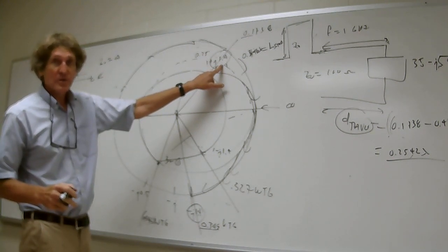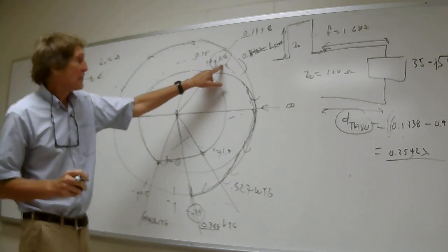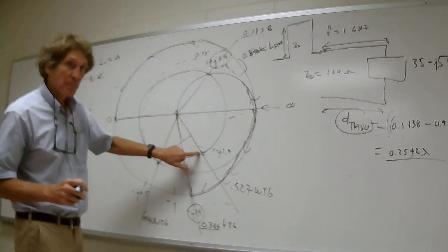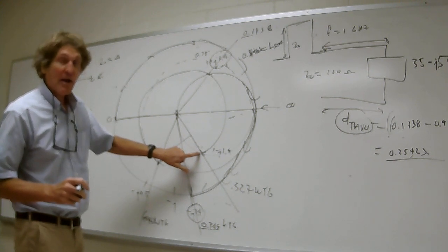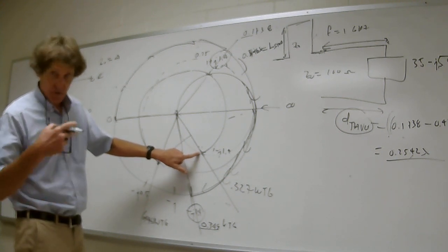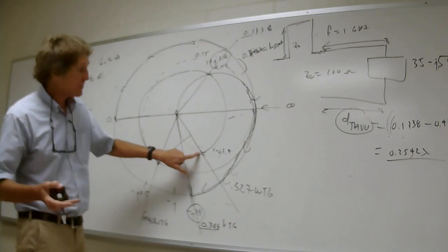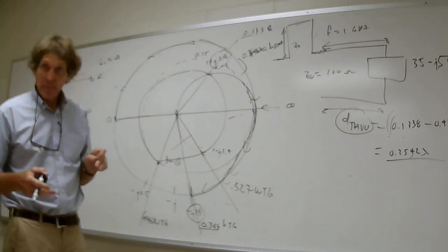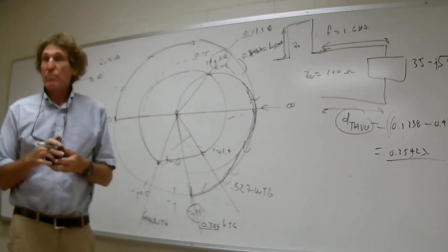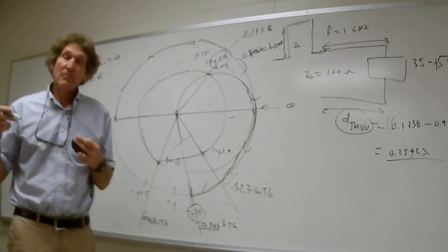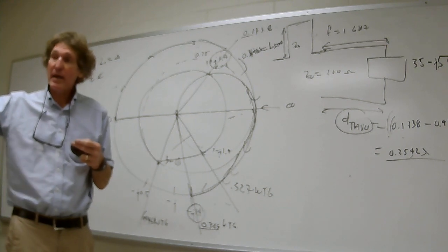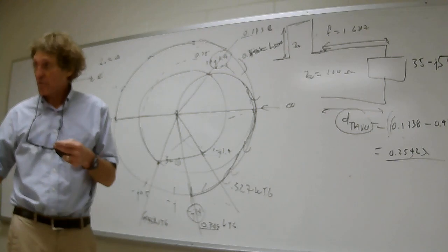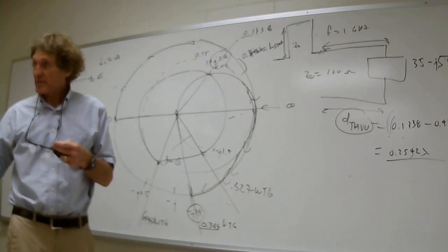Now a question for you, just listen before you're ready. If we move not to this point, but to this point here, now you would have to put an inductor in series. Do you all hear me on that? And the inductor would have to have a normalized impedance of plus J1.4. So what would the value be? It would be J omega L divided by Z naught equals J1.4, because it has to be normalized. Everybody see this, class?